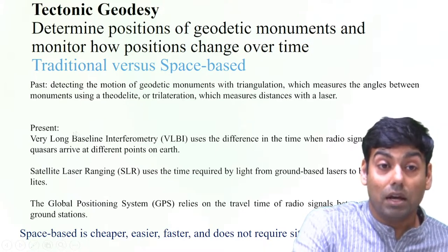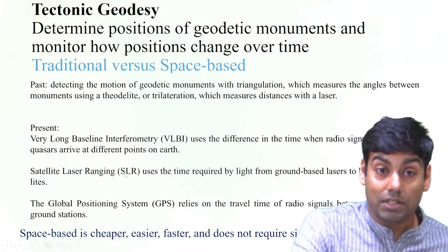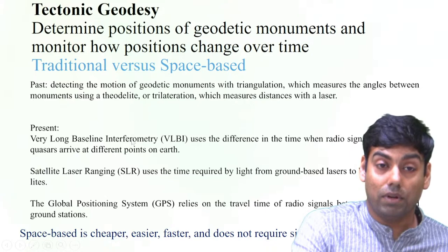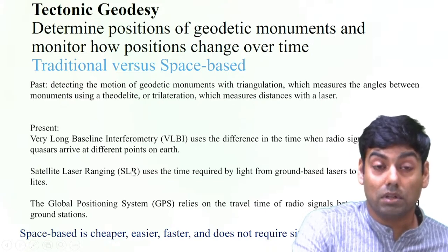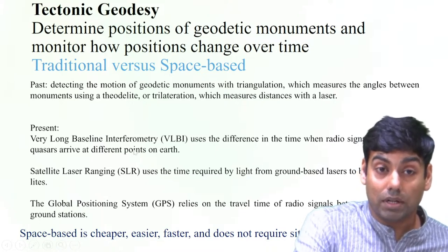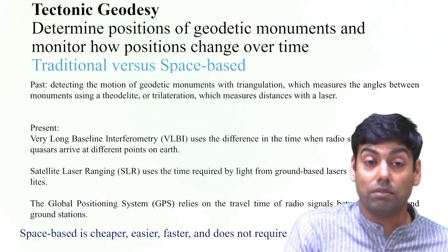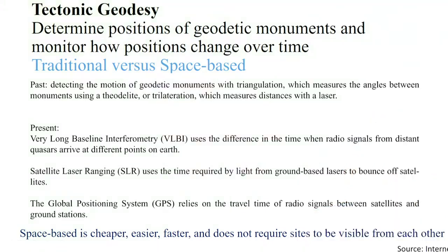Presently there are VLBI, very long baseline interferometry, and satellite laser ranging, but these two are very costly affairs. They involve huge money, and that brings limitations to our study. Then, after the operationalization of GPS, which was done in 1992, it brought a revolution in geodynamics study, giving very crucial information about movement and other phenomena to understand the mechanisms and processes.